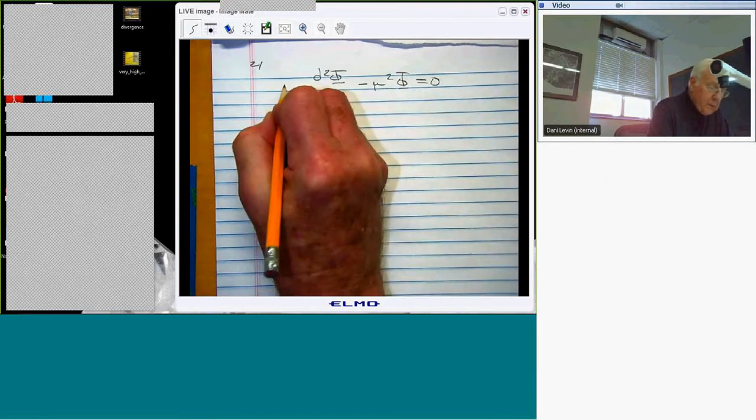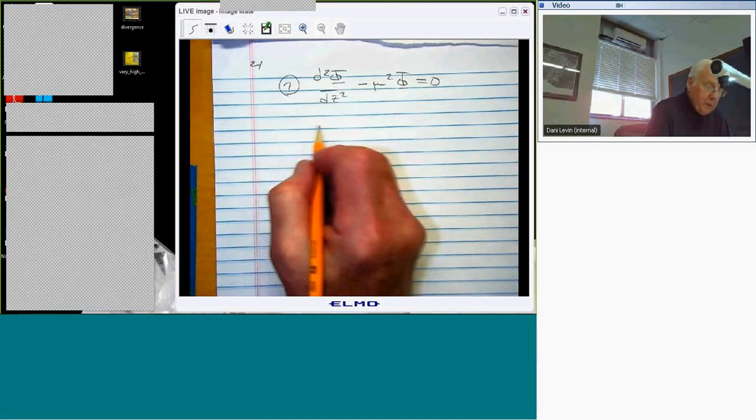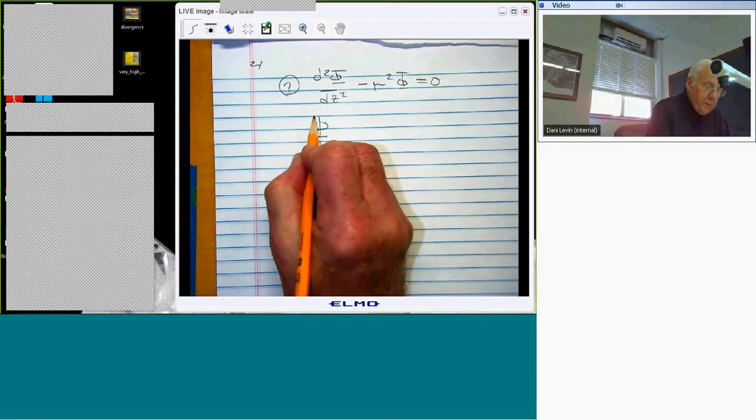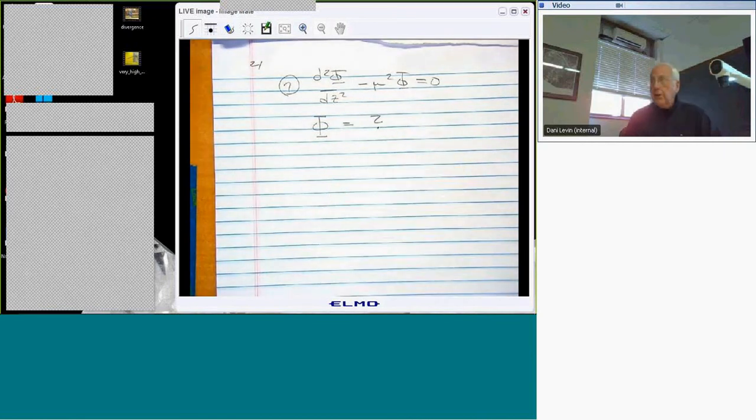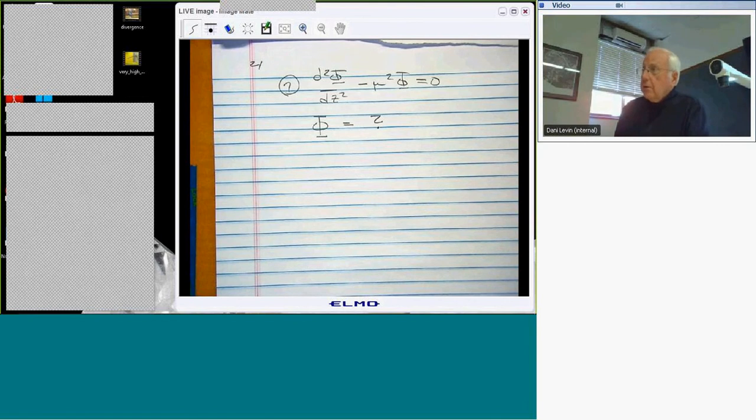This is 7. What is the form of the solution for phi? He asks. This is a linear, ordinary differential equation, second order, constant coefficients in the sense that none of the coefficients depend on z. Of course, I still got omega buried in there. I've got Mach number buried in there. I've got the Laplace transform variable p buried in there.